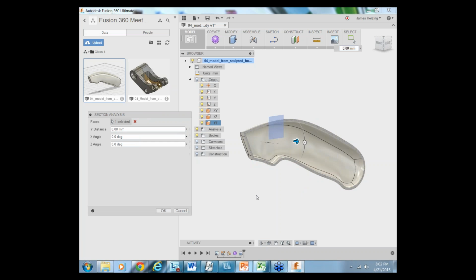In SolidWorks, when you shell, if you click on a face, it'll shell from that face on the inside. Can you do that in Fusion too? Yeah, you can select the face and have it chop that off and shell from in there as well. This is conceptually almost identical to the thicken, but different, mathematically thickening a plane with the solid.